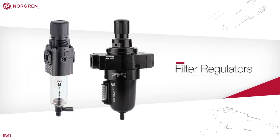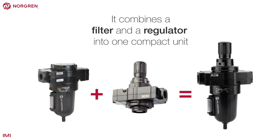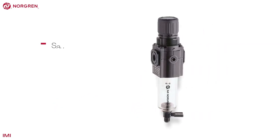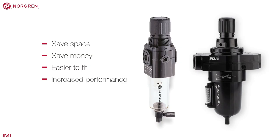The filter regulator is the most popular unit Norgren sell. It combines a filter and a regulator into one compact unit, providing a series of benefits. They save space over having units side by side, and save money as the system is cheaper than individual units. They are easier to fit, fewer connections mean less air loss, and they perform better as flow characteristics are optimized. The regulator needs to be on top and they need to be installed upright for the bowl to work correctly. So in some applications, they may not be suitable, and separate products will need to be installed.